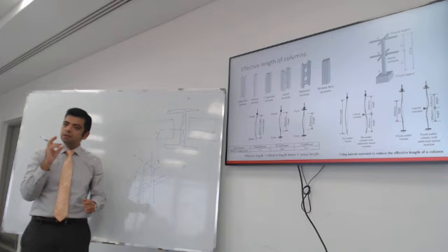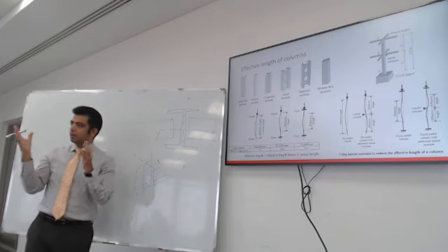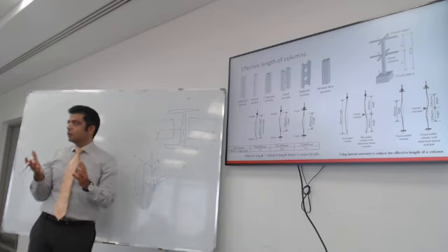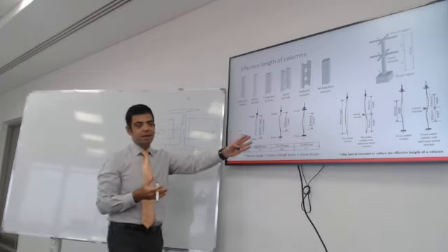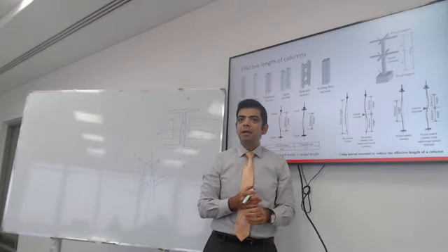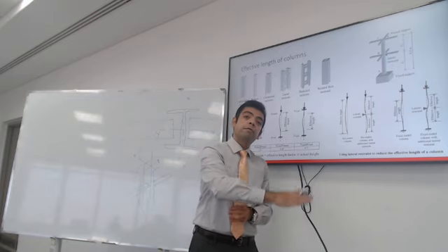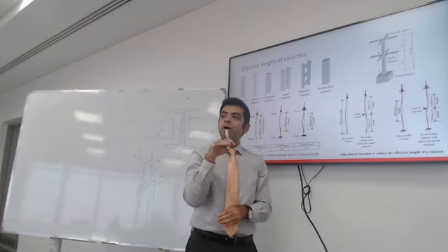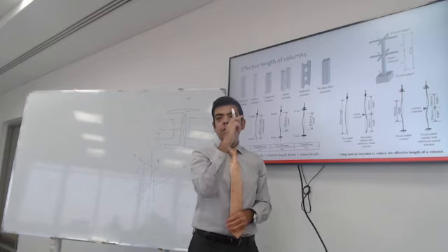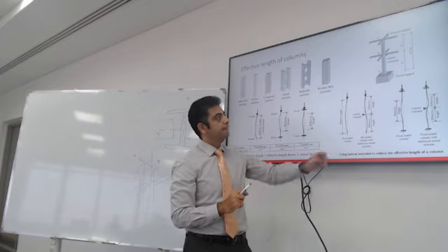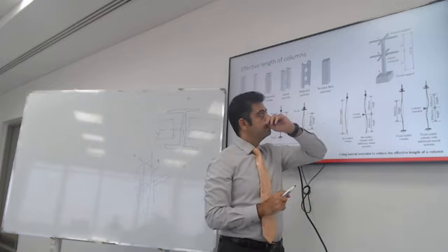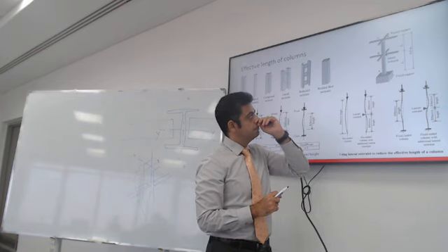It needs a little bit of imagination, or you need to visualize, in order to understand this. It's very important. If nothing is bracing the beam, the column will buckle the full length. If there are side beams, it will buckle between the beams. Like that cross, okay? If we cancel it, it's not crossed anymore. It's only from one side.